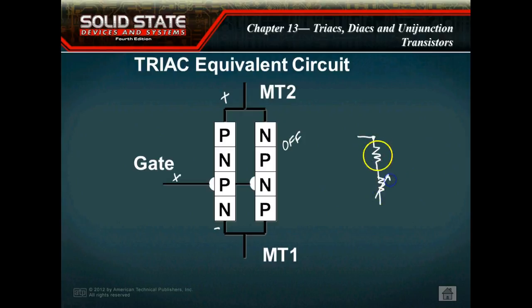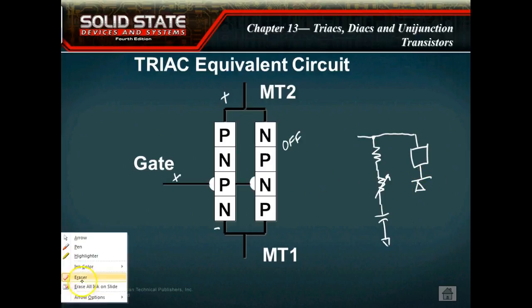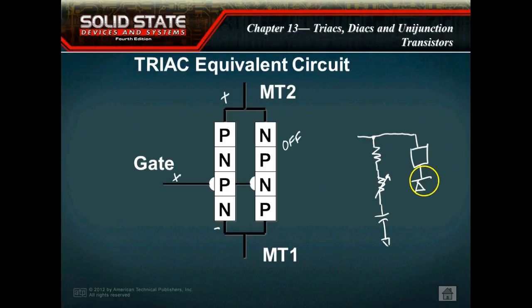By the way, this resistor is in here just so I don't short circuit. And then we'd put a little capacitor right here. And then we'd come over and put our load right up here. And then we would come in and put our triac right here. So as I draw it, right. And then we would gate it right here. So what I do when I move this, I change the firing angle.